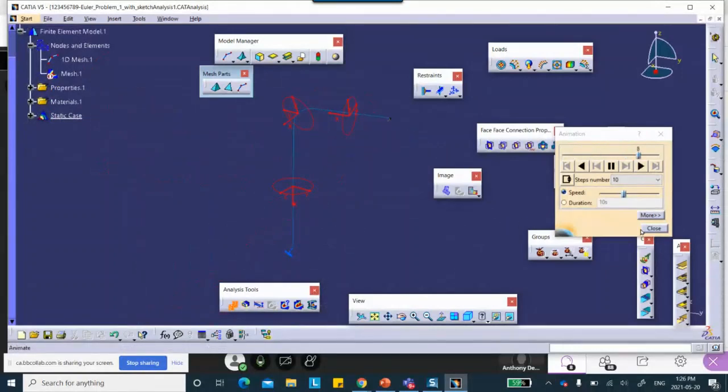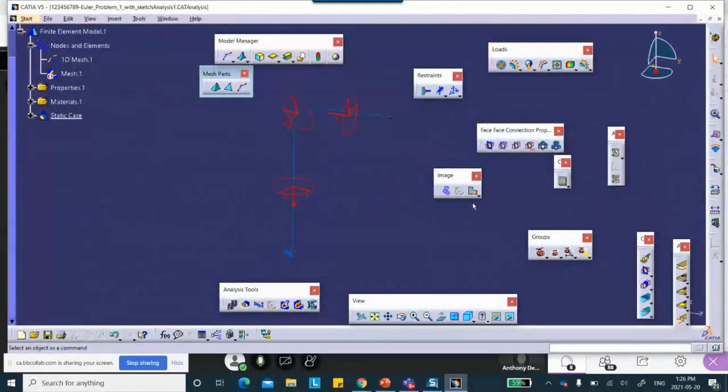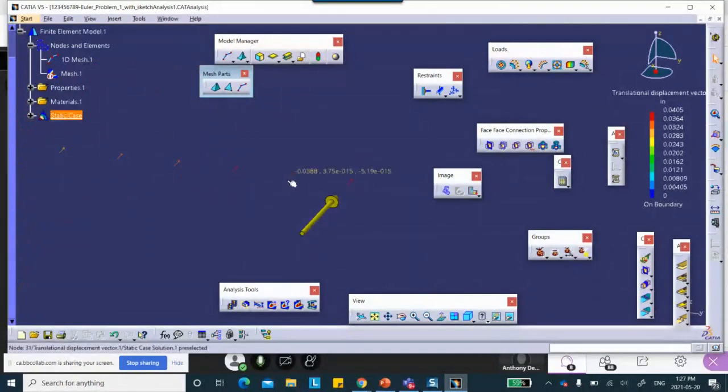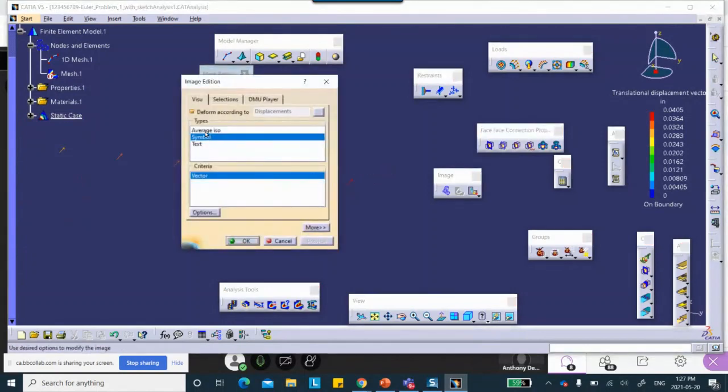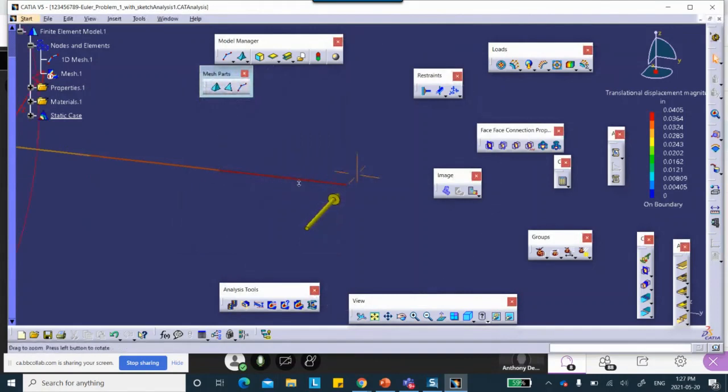Okay. Now, do you want to see the amount of displacement? There is the amount of displacement. This was called deformation. This is called displacement. That much. If you zoom in closely, you see that these are all little arrows. Each node goes by that much in that direction with these amounts. Okay. If you want to see the contour plot or contourish plot, you click on it, average ISO, and there we are. Some people prefer this over the other one.